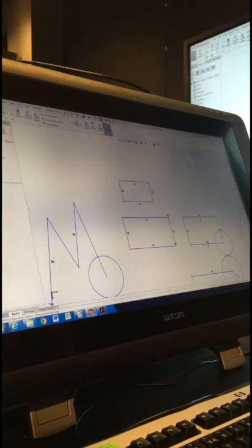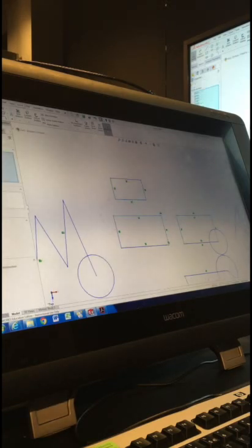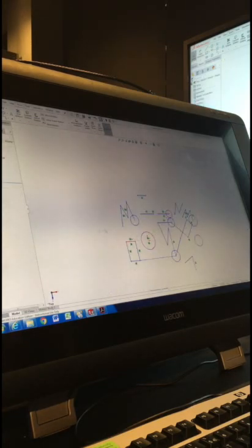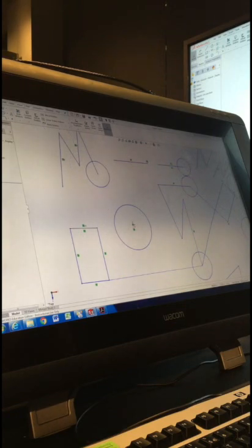If I draw that same box, but go the opposite direction, bottom right to top left, it selects everything it touches. Okay, so it can make it easy to select either way, all right, depending on what you're trying to do. Typically, you're doing a lot of selections like this because you want to clear things, delete them, but you can make that easy. Another way to select lines, a segment of lines, or a chain, is to right-click on the line and press Select Chain. And if those lines are all joined together in a chain, you can select them all and then delete or move or whatever.